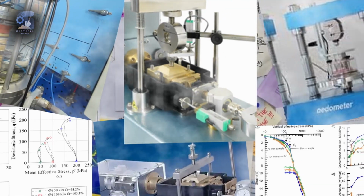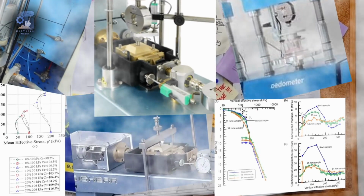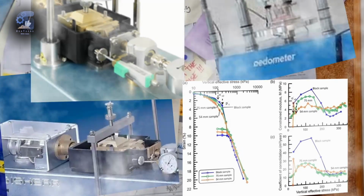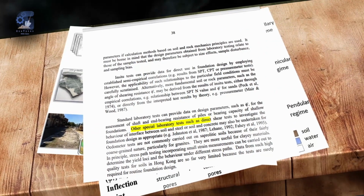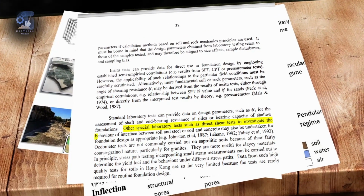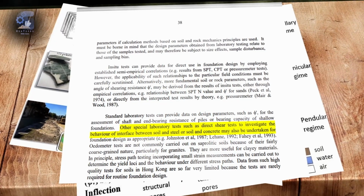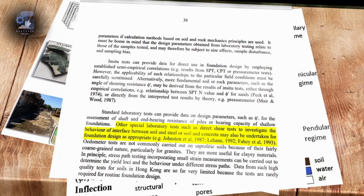These standard laboratory tests will provide data on the design parameters such as the angle of shearing resistance, an important value used to assess the shaft and the end bearing resistance of piles, and in calculating the bearing capacity of shallow foundations. Furthermore, special laboratory tests such as the direct shear tests to investigate the behavior of the interface between soils and steel or soil and concrete may also be undertaken.